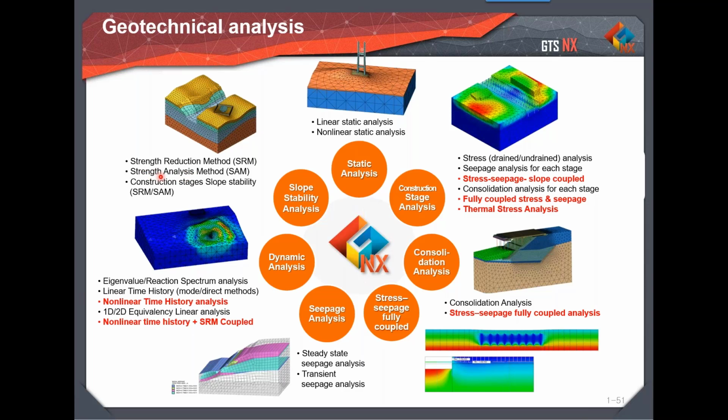So stresses are calculated according to the finite element method, but the slip circles are given according to the limit equilibrium method. So we can say it's a hybrid method, which is using the combination of FEM and LEM, FEM analysis and LEM like slip data generation. And another thing is you can do this entire analysis in construction stages, so that in each and every stage you are able to get the results of factor of safety and failure surface.